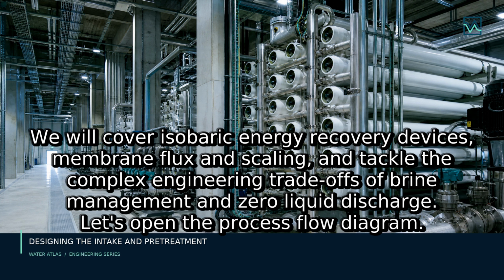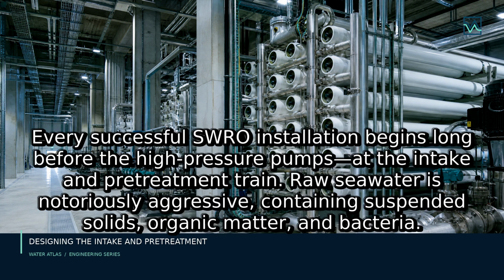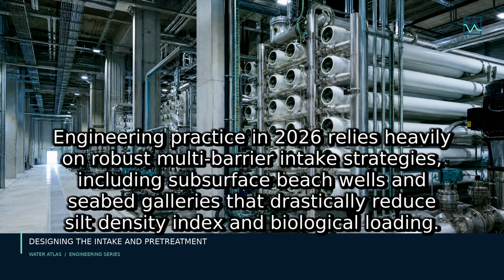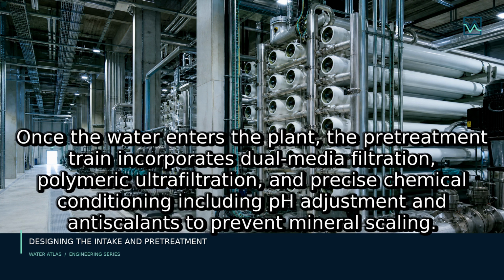Every successful SWRO installation begins long before the high-pressure pumps, at the intake and pre-treatment train. Raw seawater is notoriously aggressive. It contains suspended solids, organic matter, marine algae, and bacteria that pose an immediate threat to the downstream spiral-wound reverse osmosis elements. Engineering practice in 2026 relies heavily on robust multi-barrier intake strategies. While open ocean intakes are common, subsurface intakes, such as beach wells or seabed galleries, are increasingly preferred where hydrogeologically feasible because natural sediment filtration drastically reduces silt density index, or SDI, and biological loading.